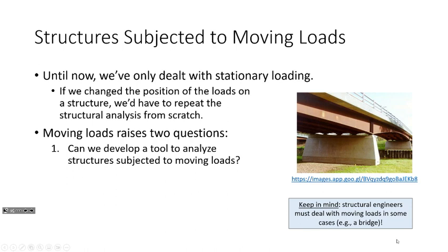We've talked before, in truss analysis, about how we can get some members that are zero force members, and one of the things I said, because we had a question, was why even have zero force members in a truss to begin with? One of the answers is that member may be a zero force member when the loads are there, and if the loads move, maybe it doesn't remain a zero force member. So that is a very real issue that we need to deal with. But just having the tool is fine. What are we going to use the tool for?